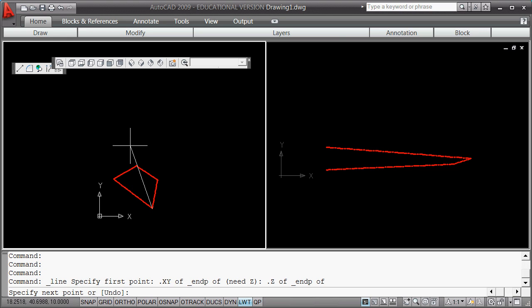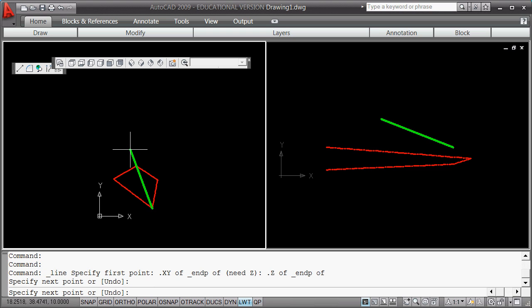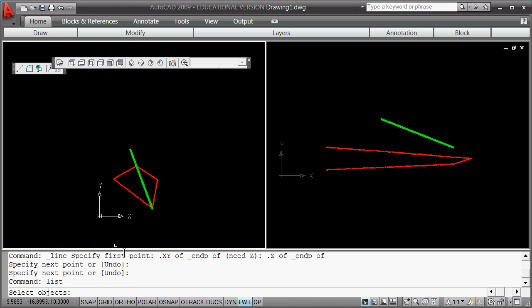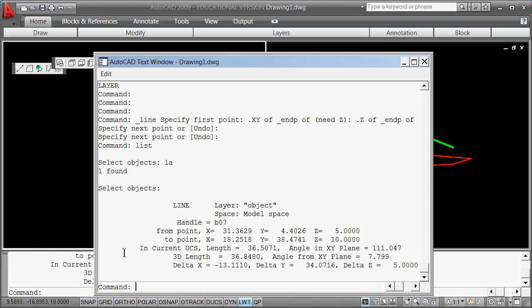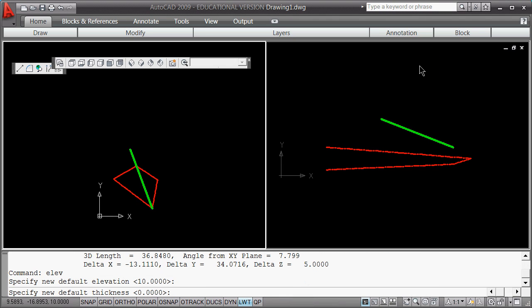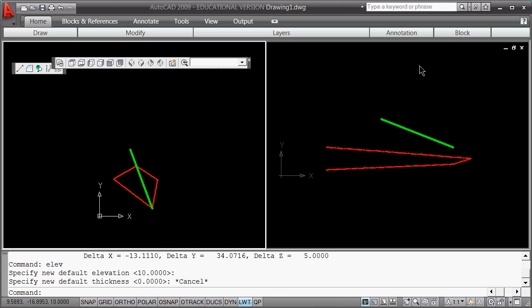And right now, without a snap, it's going to go to my current elevation, which I think we set to 5. So let me hit list. Last, a great thing to do using last, and it went from one place to the other. The elevation is 10, I think, ELEV. I set my elevation at 10. So that is what the point filters are really about. Though very often you're going to see very creative ways to do that.